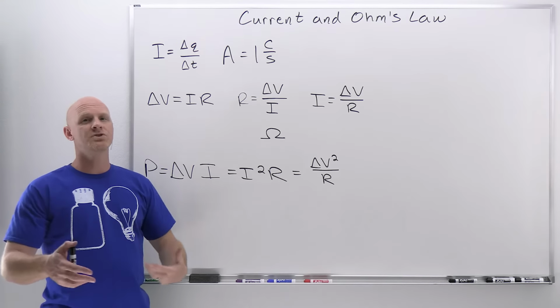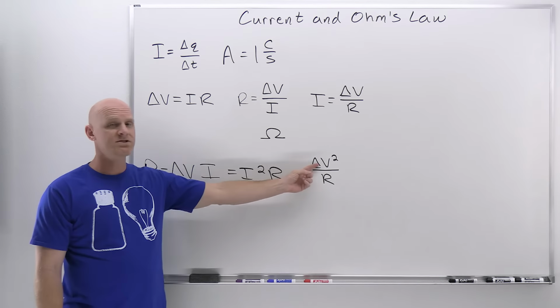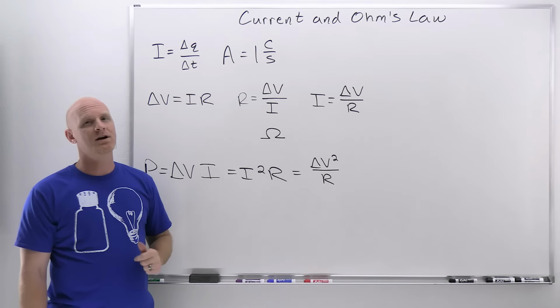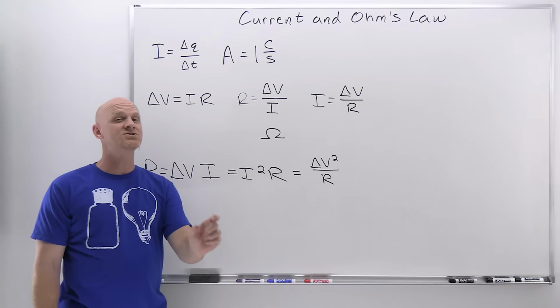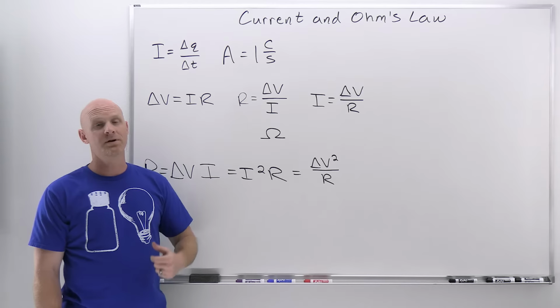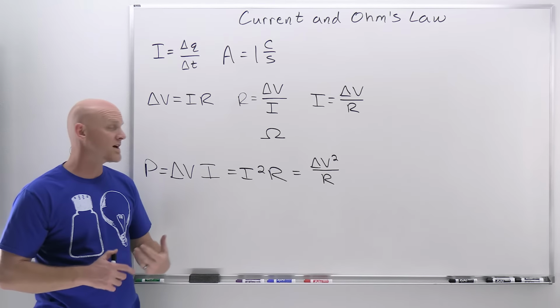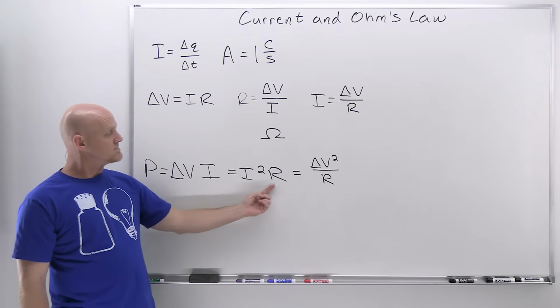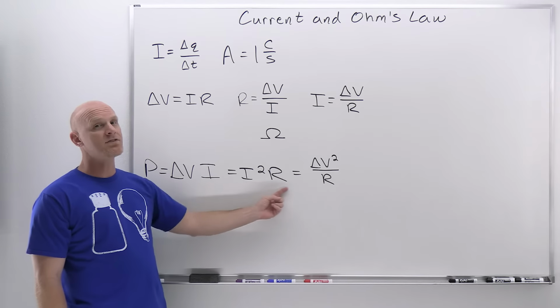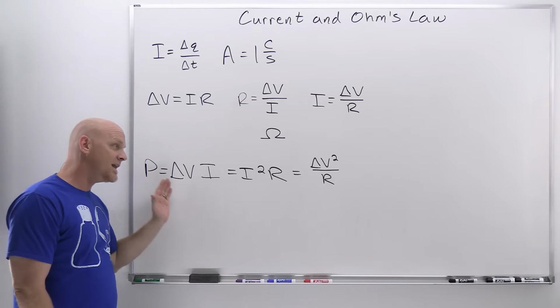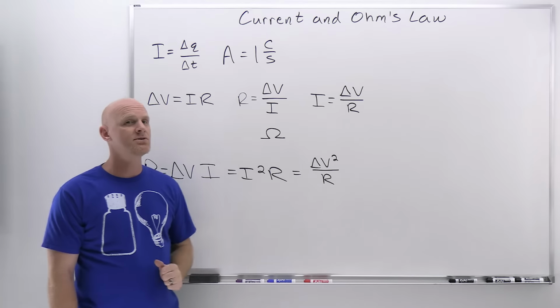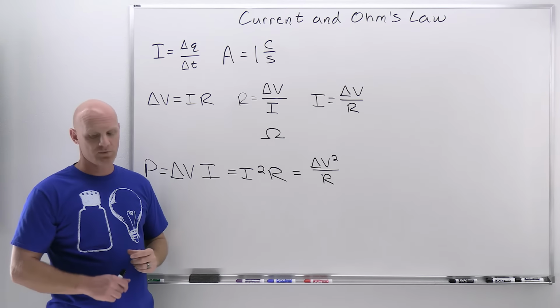And no matter what calculation they're doing on the problem, they're going to plug in 12 volts every time they see delta V. And that's where you've got to be careful. It's just the delta V off the resistor of interest in a problem, not necessarily the same thing as the delta V of the EMF source in most cases. So you've got to be careful. So I personally like this middle definition because it's impossible to make that rookie mistake. But again, technically any one of these three should give you the power dissipated across a resistor.